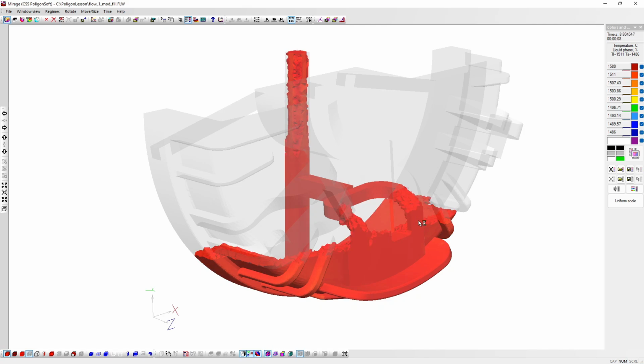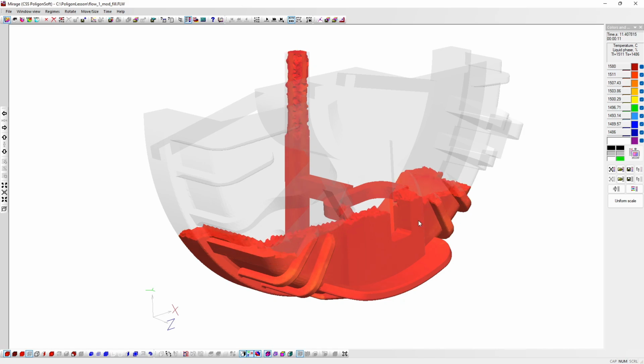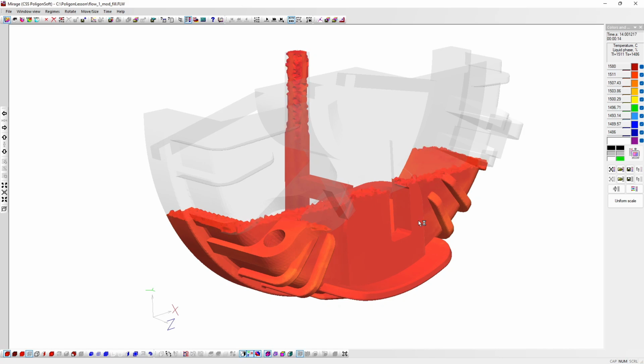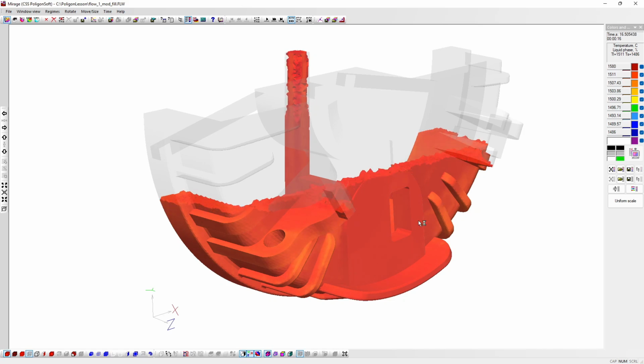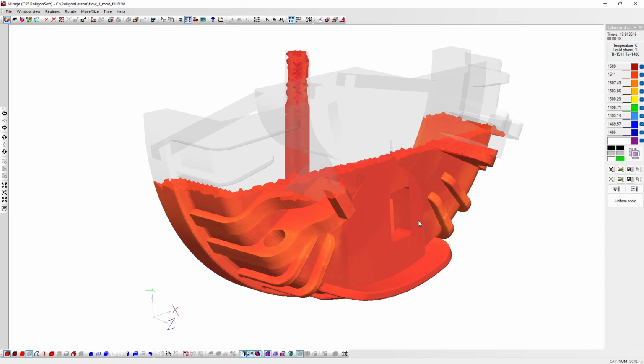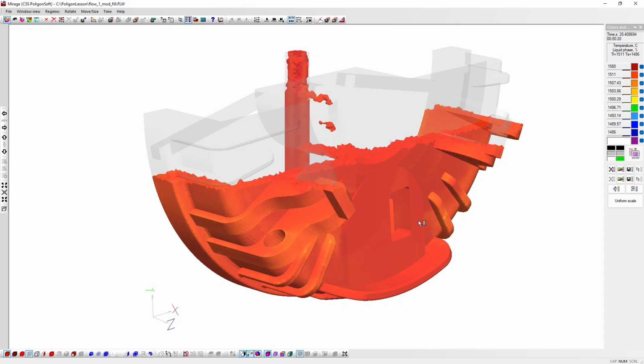The visualization of the temperature field during filling is not the most informative tool. Basically, here we can only see filling defects, in cases where the metal cools down before the mold is filled in certain areas. This situation generally occurs when there are thin-walled elements or when the molten metal is not heated enough. We have a large part without small elements, so we will not have problems with misruns. Later on, we will use the temperature field as initial data for the calculation of solidification and porosity.